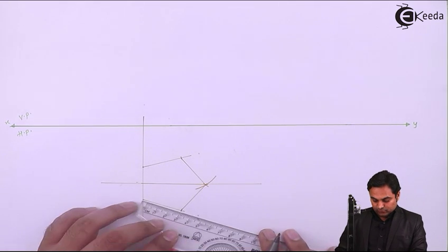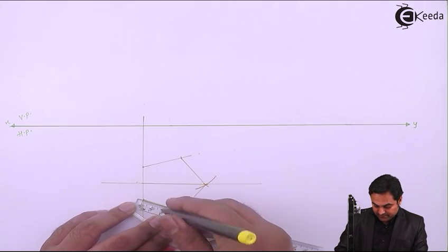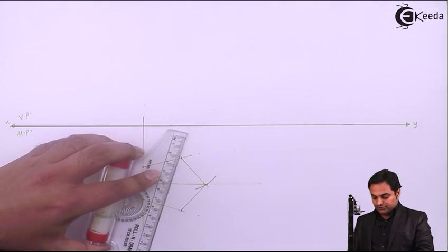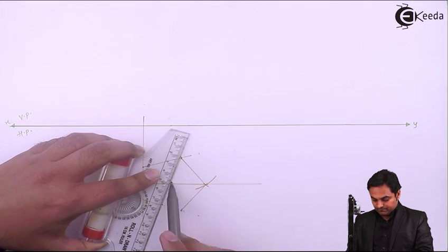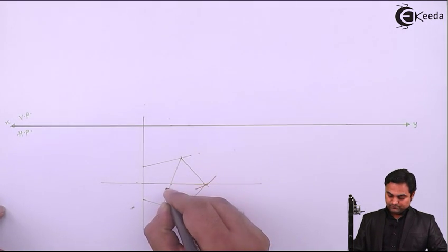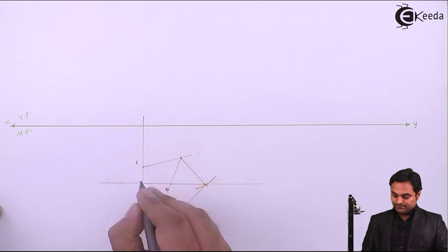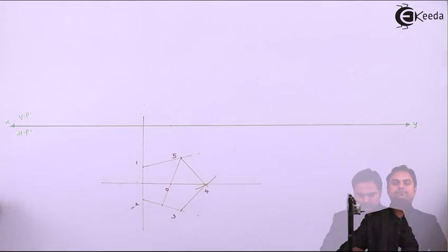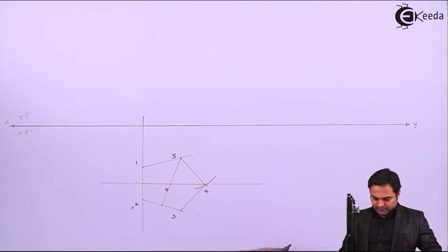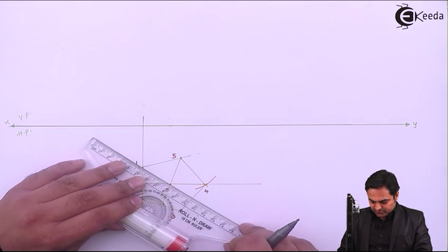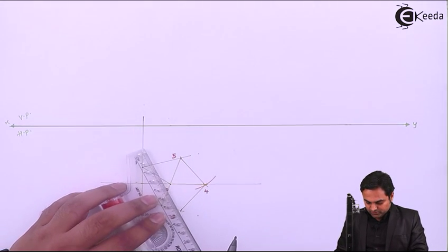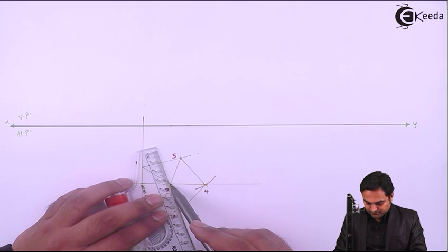Then I have to locate the apex. For that I will have to take half of any one of the sides, that is the midpoint, join it to the opposite corner. So here is the apex, point O. I'll give the notations here. Now I'll plot these points in the front view, and just before that, joining these points or corners at the apex, because here we have a pentagonal pyramid, so the slant edges are visible from top.